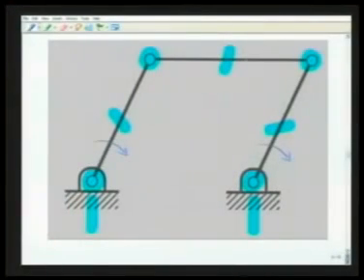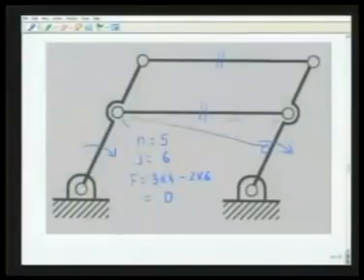In fact, such an extra coupler is normally used to drive a parallelogram mechanism. As we shall see in a model, when the parallelogram moves, there is a configuration when all the links become collinear and the mechanism loses its transmission quality. In fact, it can go into a non-parallelogram or anti-parallelogram configuration. To ensure that a parallelogram always remains a parallelogram, such an extra coupler is necessary.